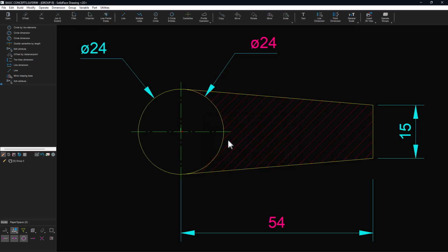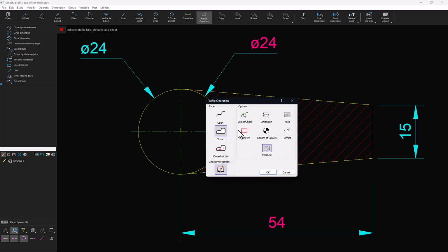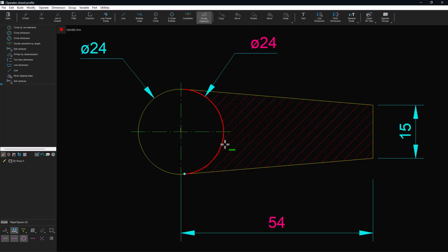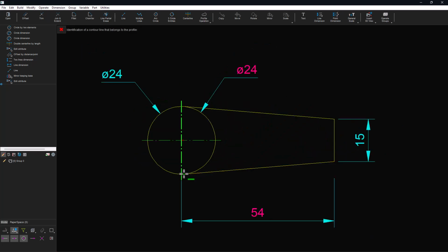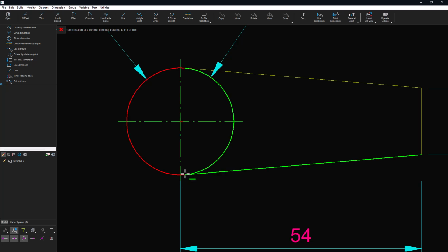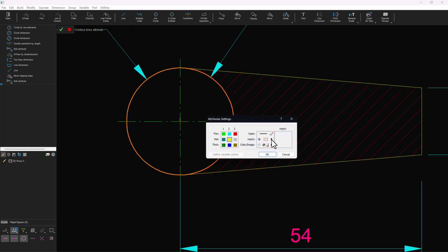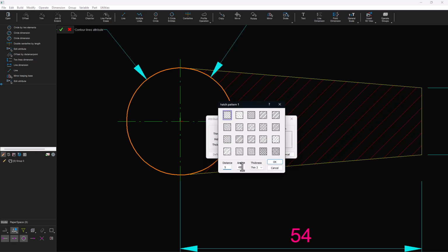See that the contour function created arcs. Select and join them with the Join option. On the left side, create another fill, but using the pattern. Define a new type, angle, and hatch distance.